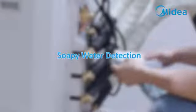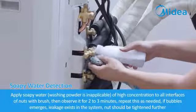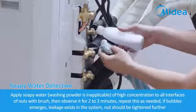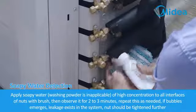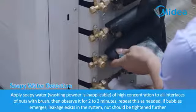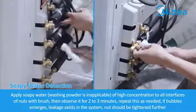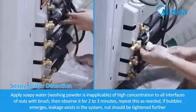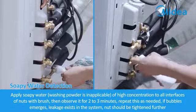Soapy water detection. Apply soapy water, washing powder is inapplicable, of high concentration to all interfaces of nuts with brush. Then observe it for 2 to 3 minutes. Repeat this as needed. If bubbles emerge, leakage exists in the system. Nut should be tightened further.